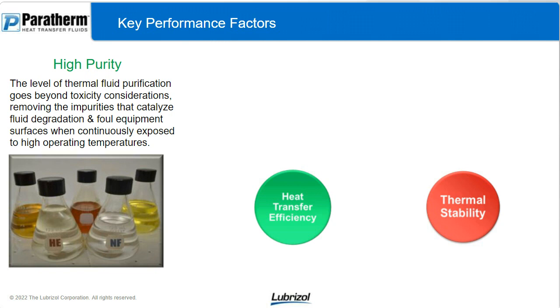So high purity is very important. You want to make sure that the fluid that you're using is able to stand up to the temperatures that you have, and the additives or impurities left from the crude oil refining process, or if something is formulated with way too many additives, those impurities are going to foul out onto the surfaces and cause problems. So you want to make sure you're specifying a high purity product.